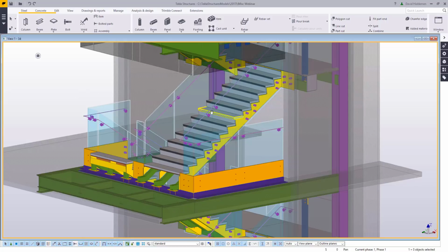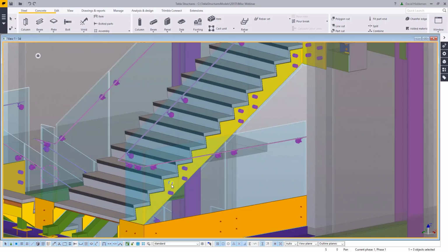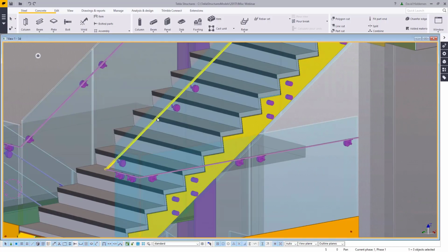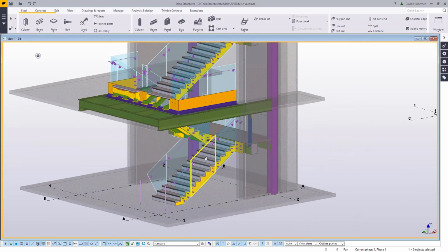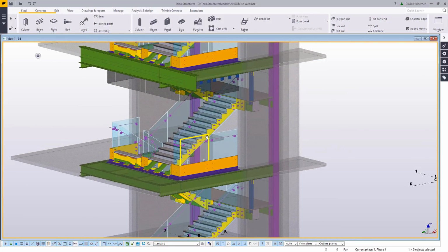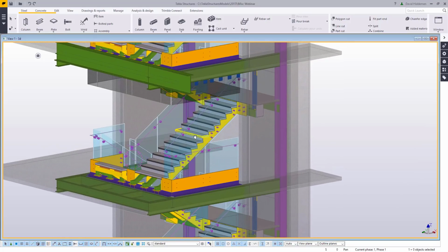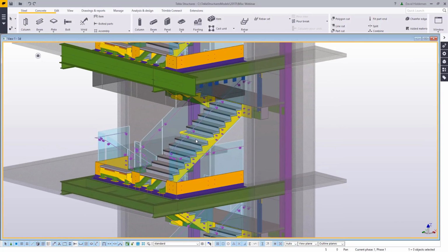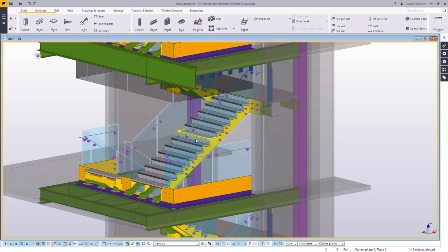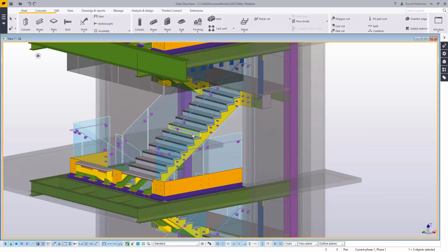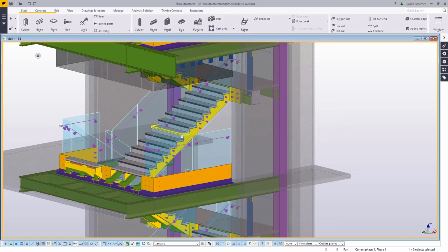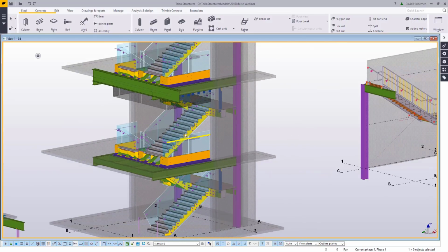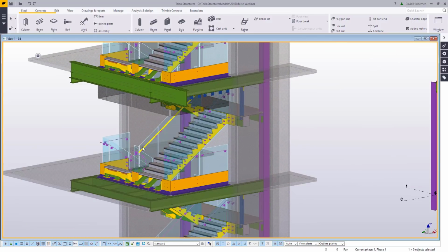We've got glass rail panels with button brackets, and button brackets for our actual handrail or grab rail. I mean, everything about this is custom. And even though you have to draw or model it the same way that you might have to draw it in CAD, all of the benefits of using Tekla Structures then pile on top of that: center of gravity, automatic BOMs, CNC information automatically generated from the model, smart intelligent drawings where your dimensioning is automated. So there's a lot of benefits even when you have to just draw it yourself.